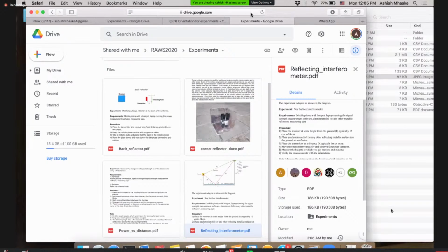Also, most of these numbers will be in log units, dBm typically, which are basically a ratio of the power to 1 milliwatt, and log of this ratio to the base 10 times 10. So you might want to convert that back into a linear scale for understanding certain aspects more clearly. So have that in mind.